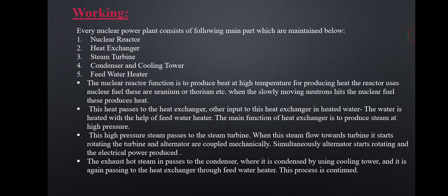Next is the heat exchanger. The hot coolant coming from the nuclear reactor flows through the tubes of the heat exchanger. In the heat exchanger, the hot coolant gives up its heat to feed water so that it can be converted into steam. After giving up heat, the coolant is again pumped back to the nuclear reactor.